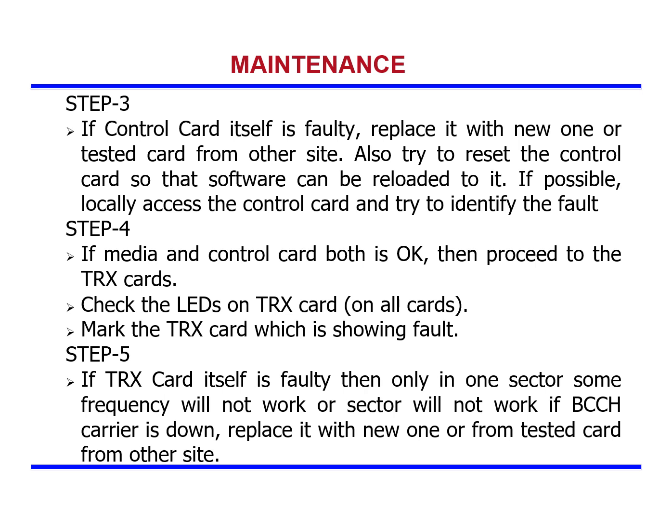Step 3. If the control card itself is faulty, replace it with a new one or a tested card from another site. Also try to reset the control card so that software can be reloaded to it. If possible, locally access the control card and try to identify the fault.